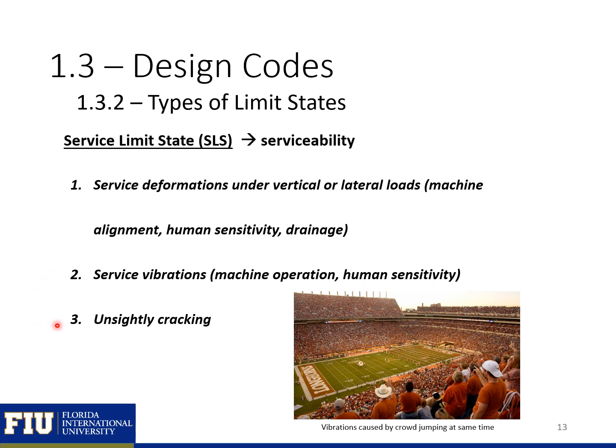And then we also have unsightly cracking. So cracking may not be a reason for concern for the engineer, but it can make the user feel uneasy about the safety of a structure. So we need to be conscious of how our structure behaves under service loading so that our users feel safe and comfortable in the structures.